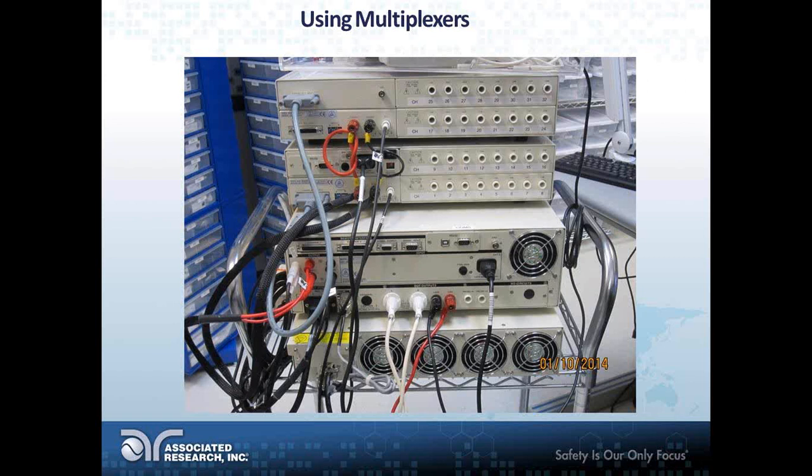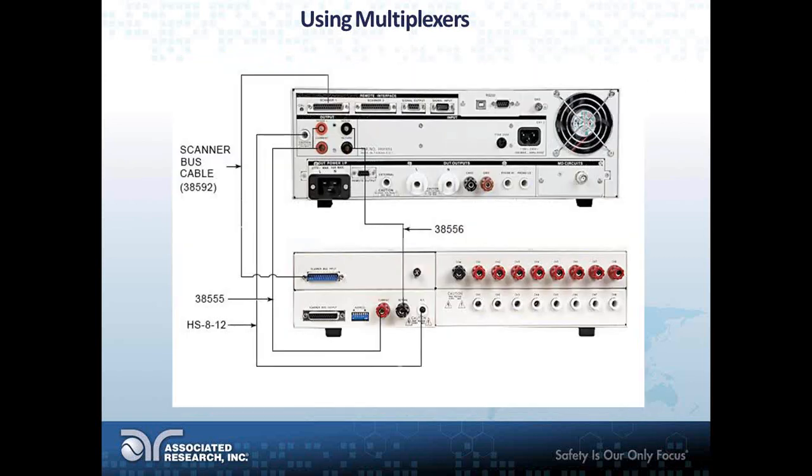An electrical safety testing instrument with an internal scanning matrix is basically a much more cost-effective solution for manufacturers with the need for multi-point testing applications who wish to increase productivity and improve safety. But again, if there's a need for adding more channels or more test points, using external boxes is an option, and using a master-slave configuration can basically allow you to test an infinite number of test points.